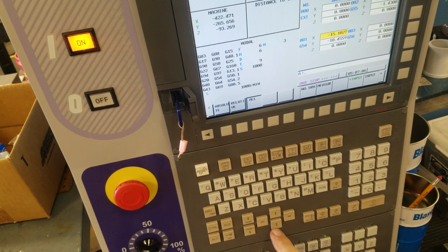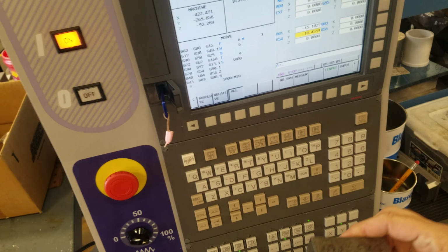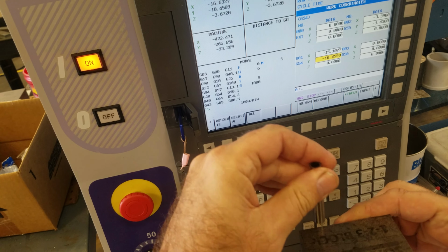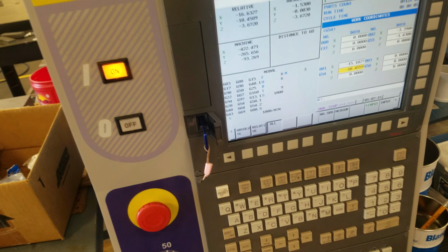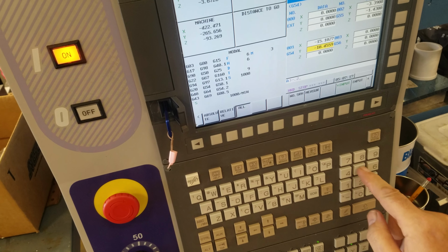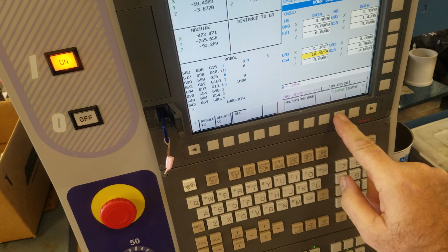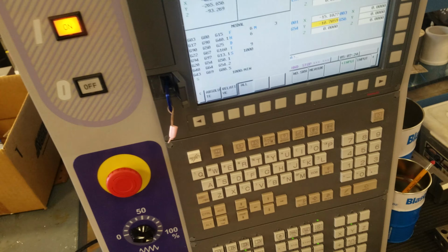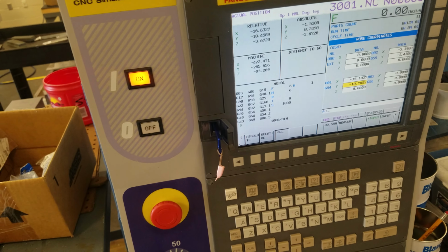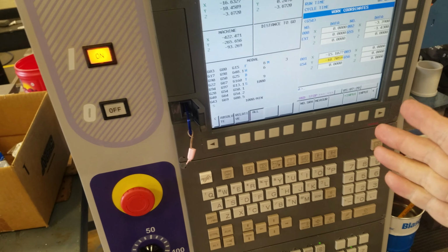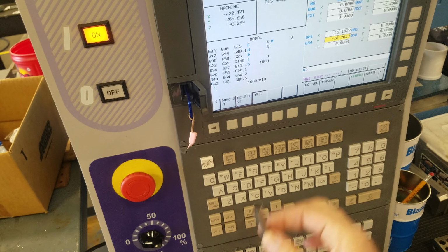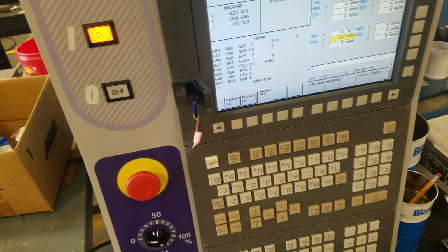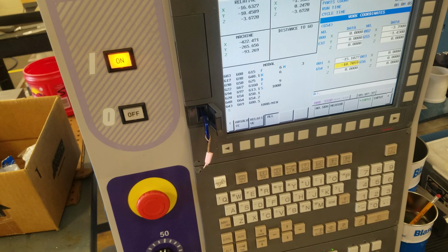That is now adjusted. And say I was doing this corner here and I was edge finding and I was shifting in this direction. That's a negative shift. So I'm going to go negative 0.250 input plus. Okay, execute. That's now adjusted. Some other ones will use the relative screen and re-zero and re-shift, but I like doing the edge find, get the number, and do the math to shift it. All right, so that'll do X and Y.